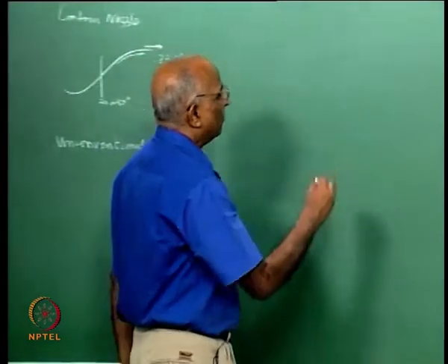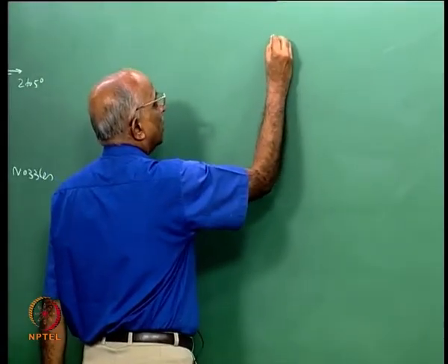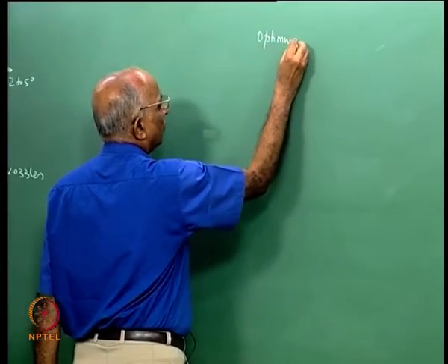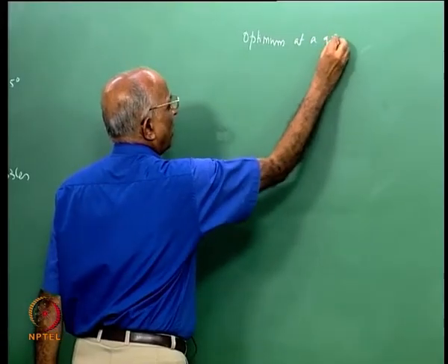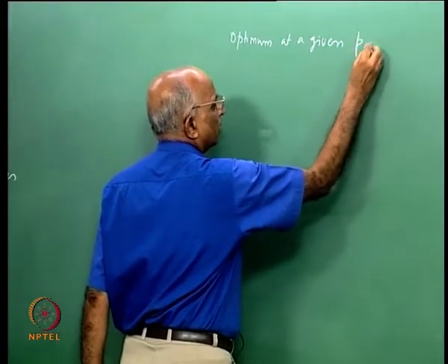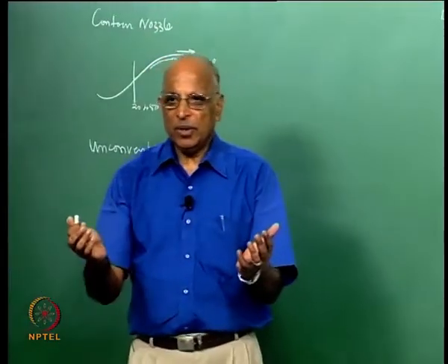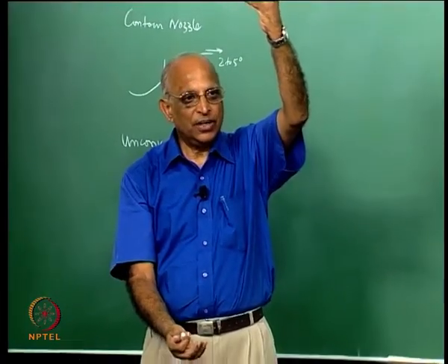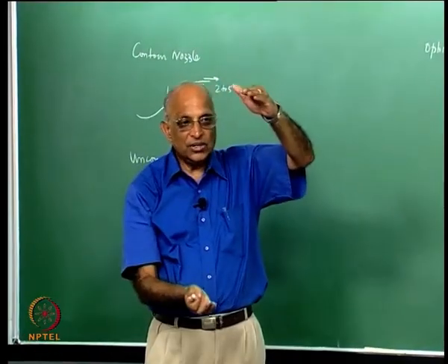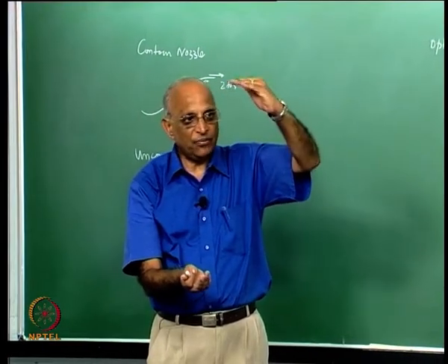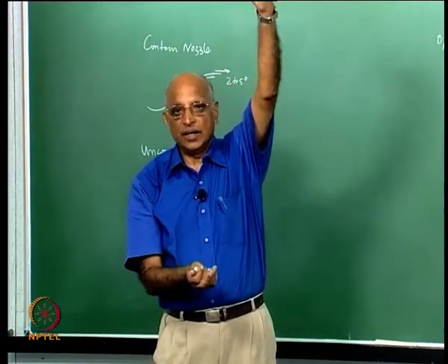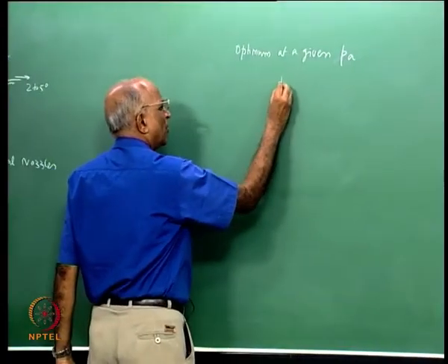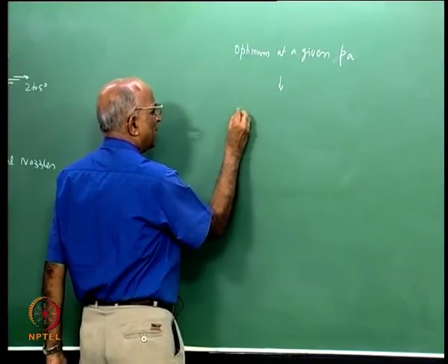First I can tell myself, well, a nozzle operates at its optimum at a given value of ambient pressure. In other words, if I want to make a nozzle, I design it for, let us say, 15 kilometers, start operating it from 0 kilometers and the rocket goes up to 30 kilometers. Initially 0 to 15 it is not optimum, at 15 it is optimum, beyond 15 again it is under expanded and not optimum. Therefore, can I have something like an extendable nozzle.